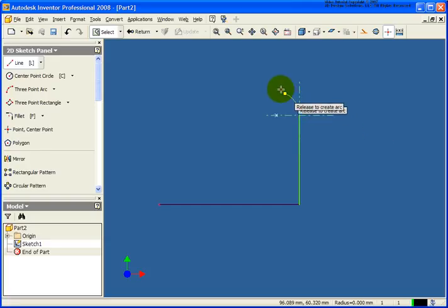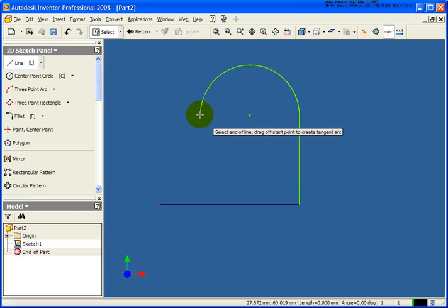So I'm going to go back to where I was in the very first place. And as I'm sketching, you'll notice that I'm also getting these dotted lines. Those are referred to as inferred points. So it's basically telling me in this case, if I select that point right there, it will be positioned to the left, or horizontally, to that last point. However, it will not apply a constraint. So I could go back and drag that later.